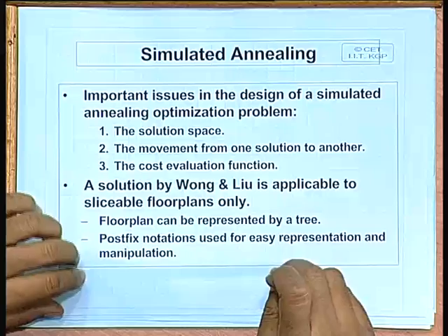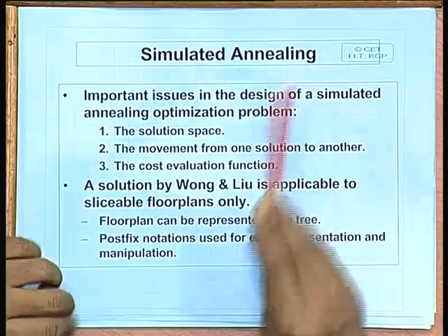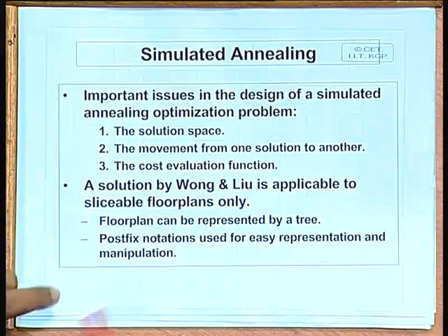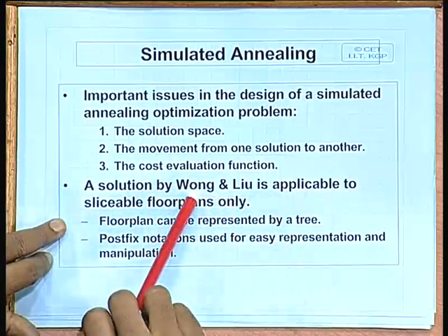Now, in the floor planning problem also, simulated annealing has been tried out by many researchers. There have been several different ways of modeling the problem, defining the moves, evaluating the cost function. But what we will be discussing is a very interesting approach which was proposed by Wong and Liu.